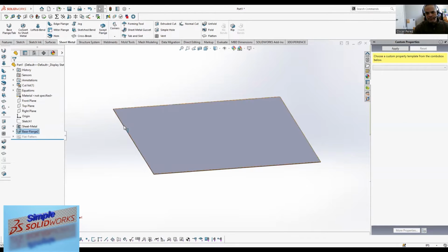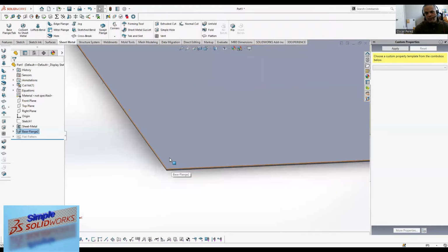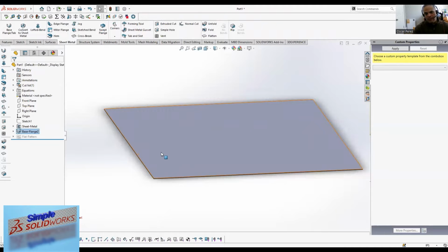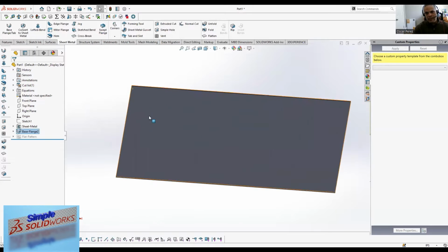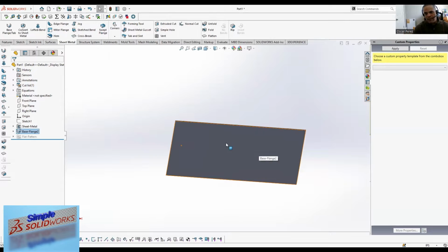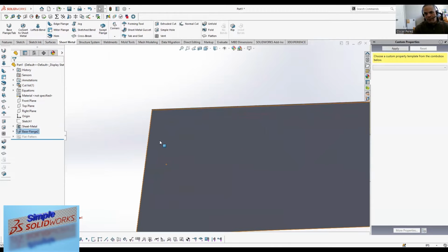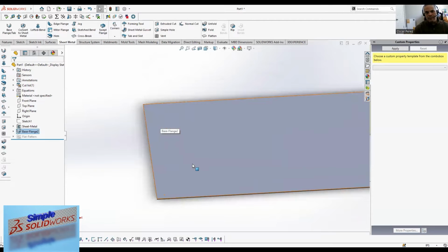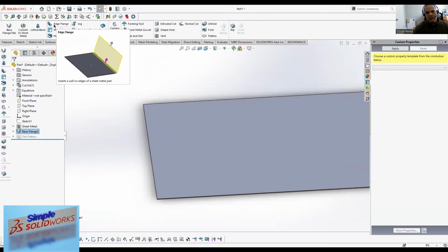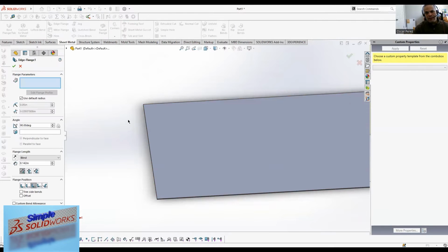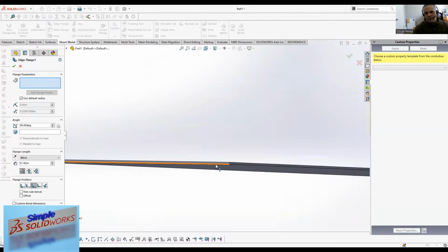Okay, so again, it's important that you follow how you want this thing to be bent, right? If this is going to be where the plastic is being laid out, then you want to protect this area. So you want the bend to be done facing down so that all the scratching from the surface of the press brake is going to be on this surface while it's protecting the plastic side, which is going to keep it nice and pretty. So it all depends on how you want to do it. If the inside of the box is what you want to keep pretty, then you want to have your flanges facing up.